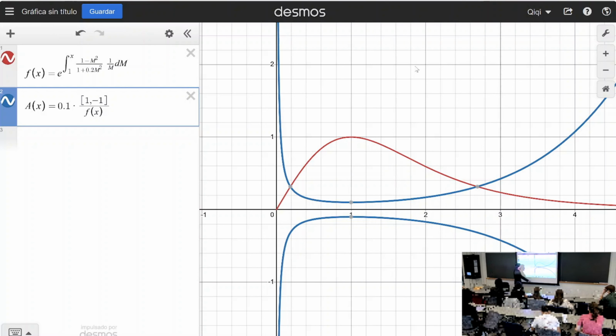For any shape, if I have an arbitrary convergent divergent nozzle, you can look up the area of that nozzle and map it, assuming the same throat area. So this is the throat area. Assuming the same throat area for any nozzle shape, you can map the area to here and find out what the Mach number is at that particular section. All right. Questions?